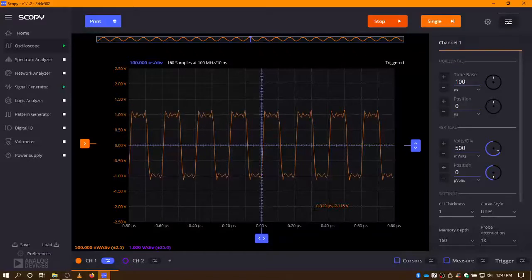The bandwidth is what we call the 3 dB point, or where your signal is down from its maximum to 0.707. So if you had a 1 volt RMS signal, you would actually see 0.707 volts. So those are key factors to keep in mind, whether you're using the USB digitizing style of oscilloscope or a piece of bench equipment oscilloscope. You have to look at that bandwidth, and like I said, rule of thumb is only a third of it is good for actual measurements.